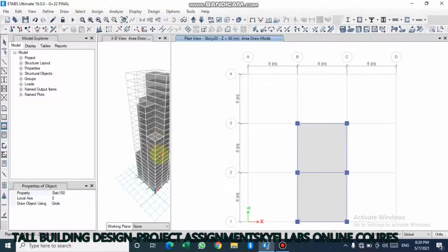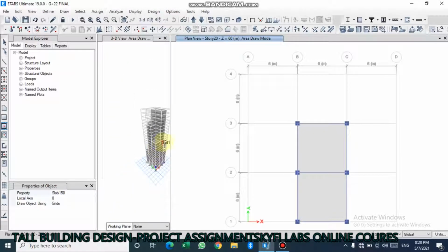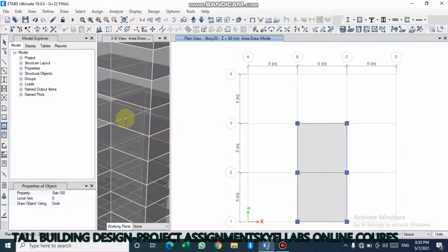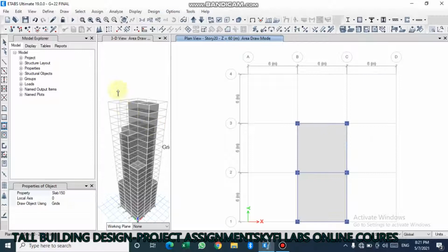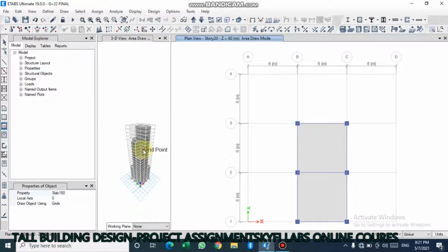Here we have not drawn any shear walls or partition walls. We have drawn auto cladding. They are helpful in applying wind loads, as in this project we have applied wind load. They don't have any self weight, but in this project we have considered a self load for cladding as 0.2 newton per mm square. So now, after creating the cladding, we'll assign loads to the structure.